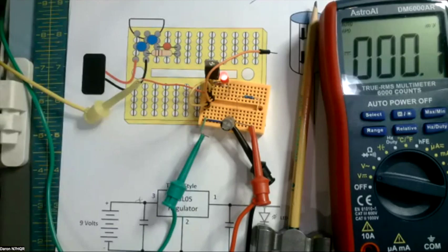0.632, or 63.2% of 5 volts. Have you figured out what that is? No. Okay, hang on just a second. And that's going to happen in 5 seconds? 3 something volts. Yeah, wait a minute. 5 times 0.632 equals 3.16 volts.